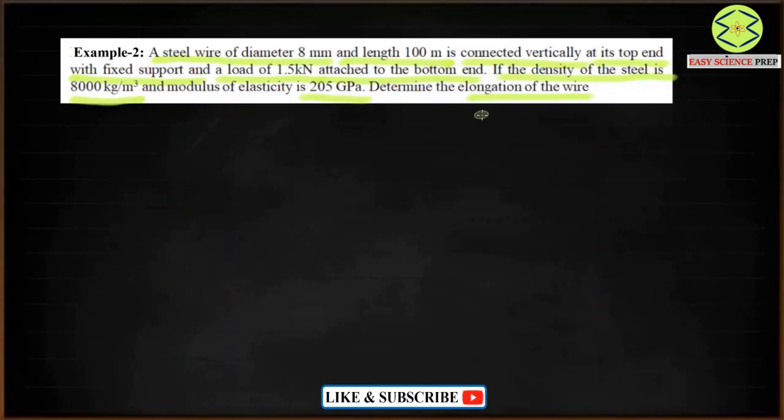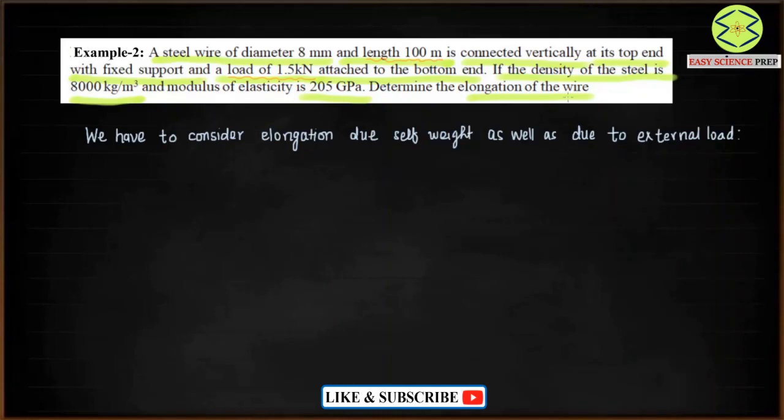If you read here carefully, there is an external load of 1.5 kilonewton attached, and we also have a huge length of wire, that is 100 meters. In this situation, we cannot neglect the elongation due to its self weight, because there is a 100-meter length involved. So here we have to consider elongation due to self weight as well as due to external load. This is an important point to note.